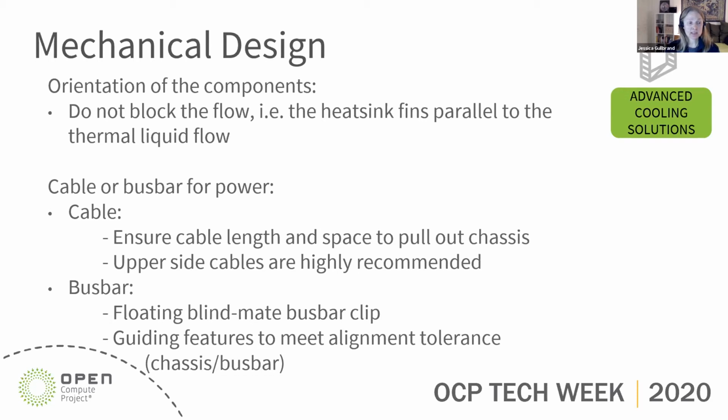If you're dealing with bus bars, you can use the floating blind mate bus bar clip. And of course, it's recommended to have guiding features to be able to meet alignment tolerances when you're mating the chassis and the bus bar. So those are some of the considerations there.